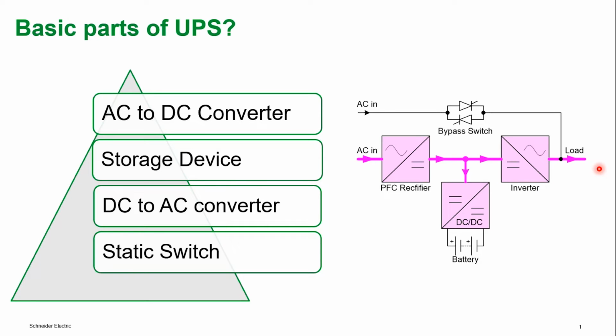They all require alternating power supply for their operations. They will not run on the direct current provided by the battery bank. So we need an inverter section which will convert direct current into alternating current, and hence it is given to the load, and whatever equipment is connected to our UPS will work without any further hassle.